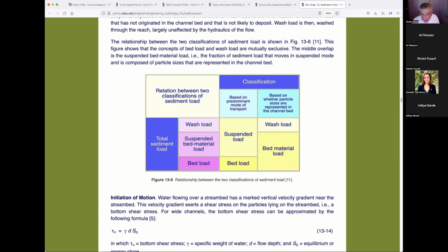There are, that I know of, about 50 formulas for sediment transport that have been put together over the years. One of the earliest, I believe, was Shockley's formula, dated around the turn of last century, so about 100 to 120 years ago. But of the many formulas by proper name, the most well recognized are the Einstein formula, the modified Einstein formula, and the Kolbe formula.